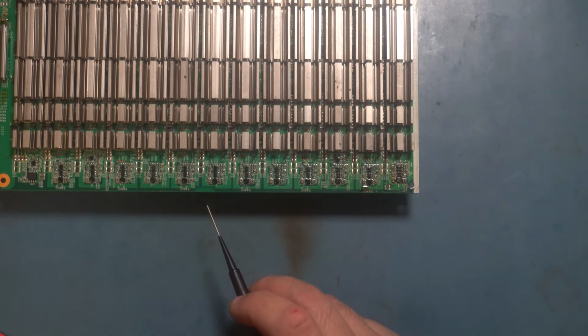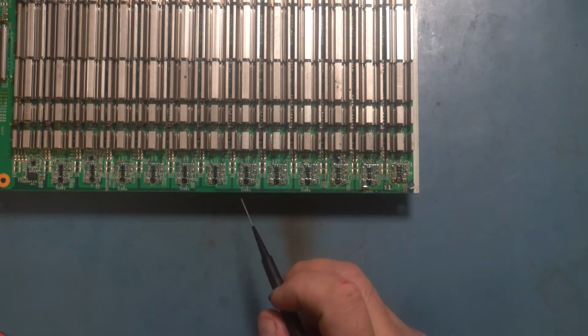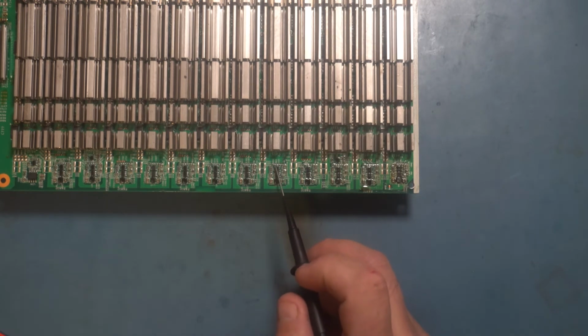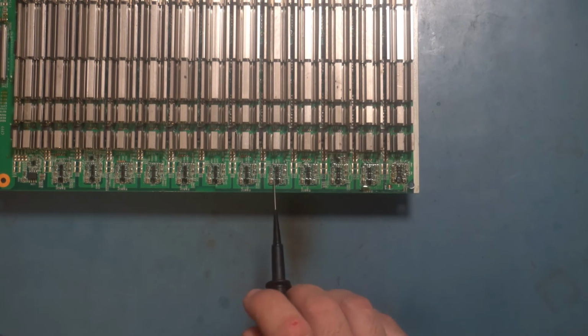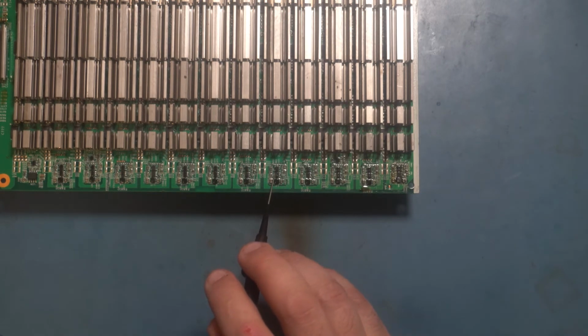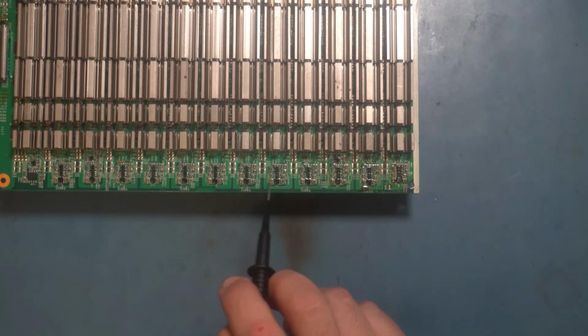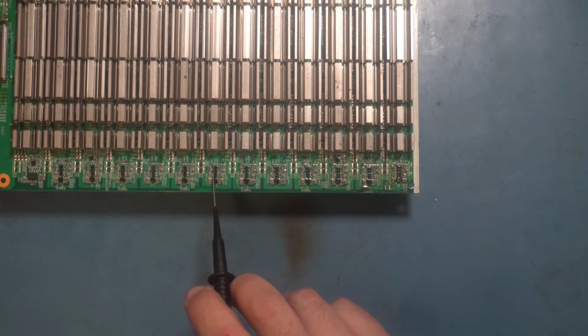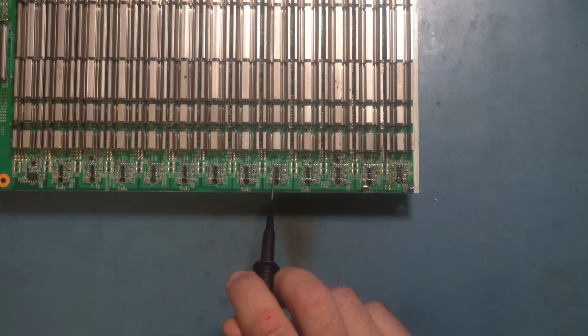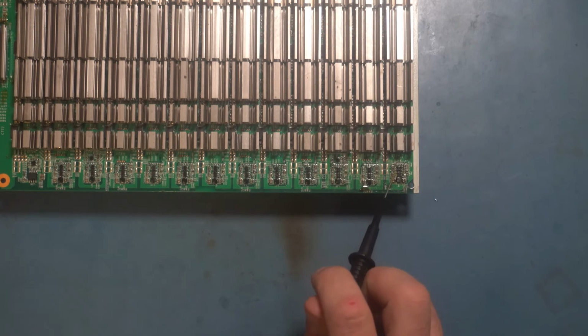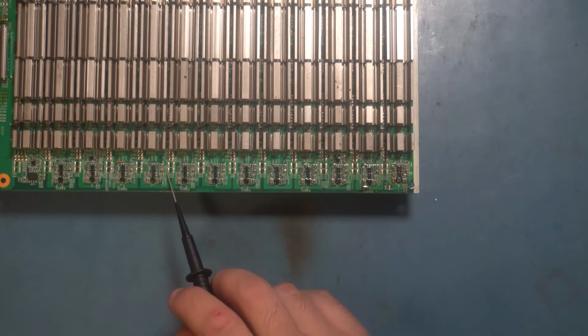And the more overhead you have, the more room you have to do some filtering and cleaning up of power and all that kind of stuff. So all that to say, and again, the input of those LDOs are dependent on the model, but usually in some cases they would take the voltage from a couple domains above, right? So if we have 1.6 volt per domain, the input 2 domains above would be 3.2 volts. And so that LDO would be regulating 3.2 volts down to 1.8.